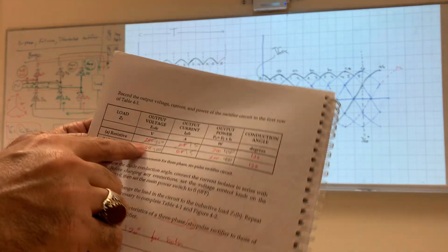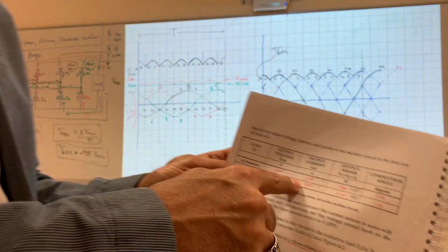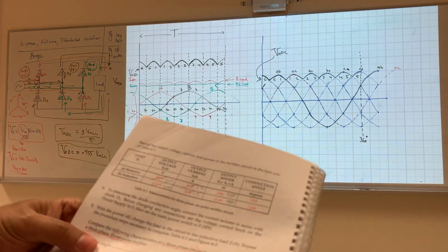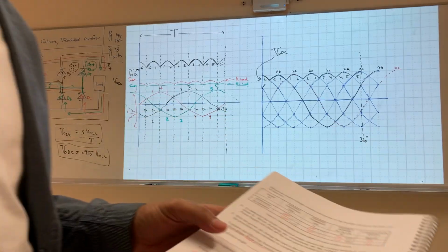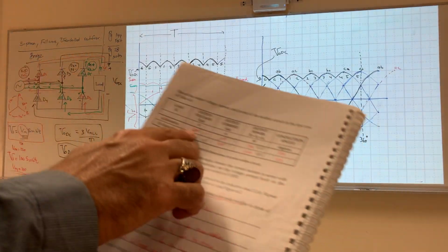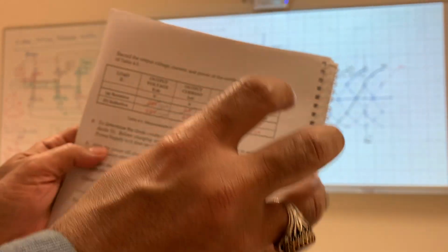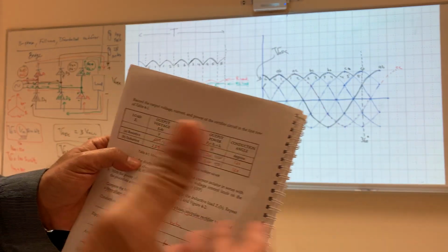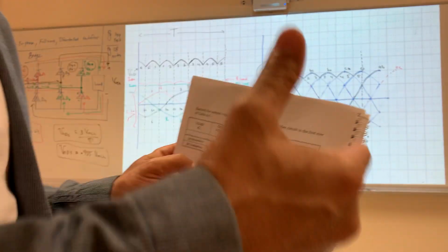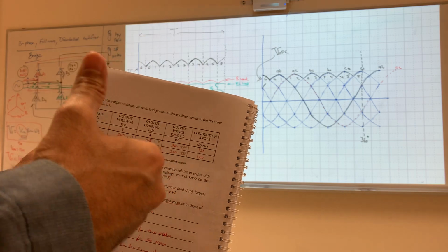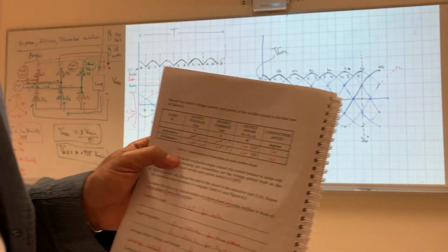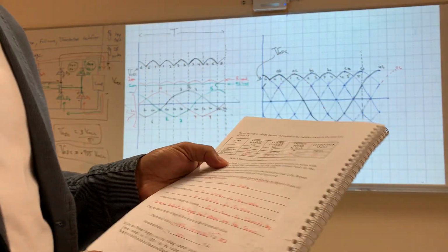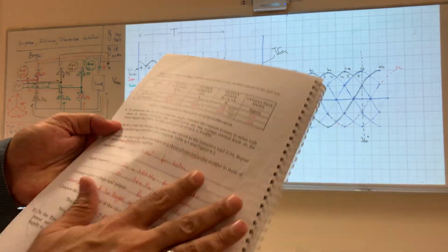You will notice that the output voltage is between 250 and 300, but it's mainly 250. And the rated value for each resistive box is 120. So if we use it for a long time, the resistive box can be damaged. So we will use 2 in series. So 120 plus 120 will be 240, so it can handle our voltage. Okay? And you're gonna do the same here.